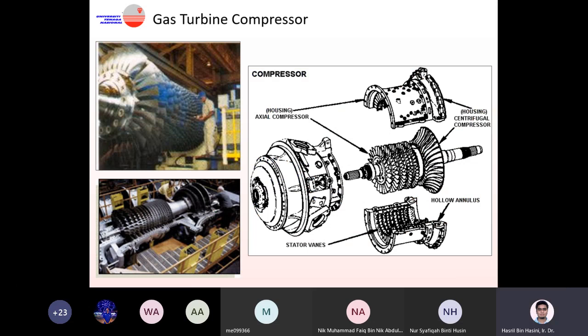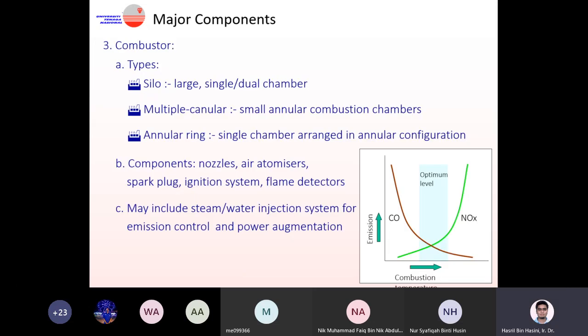Okay, this is a figure that shows a compressor blade. You can see, this is an example for a gas turbine. This is the compressor blade, and then towards the end here, you have a turbine blade. The turbine may have maybe 3 rows, while the compressor may have 8 or 10 rows of blades. That is the reason I mentioned just now: you have to increase the pressure slowly. You cannot simply increase it suddenly up to the higher pressure.